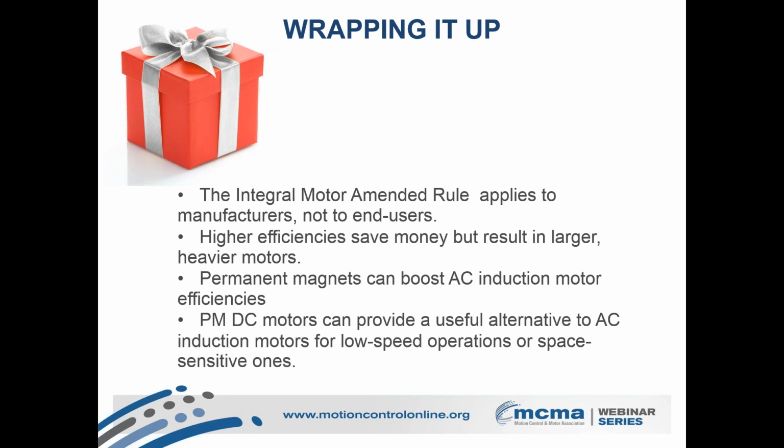So, sum total to me, the Integral Motor Amended Rule applies to manufacturers, not end users. If you're an end user, hopefully you have been thinking about this for a while and making your switch over, but if not, and if you go to buy a replacement motor after Monday, you might be in for a little surprise when it shows up, because it's not going to be quite like you expected.